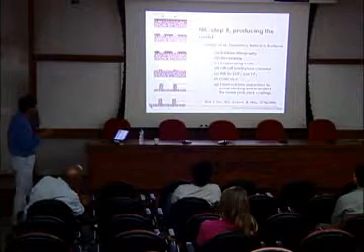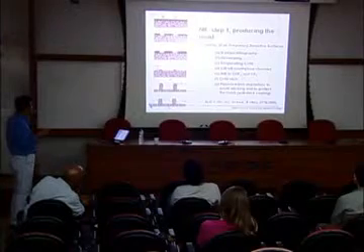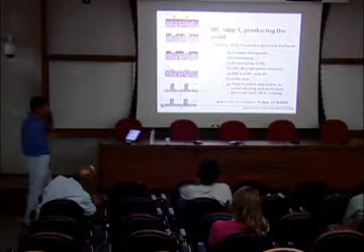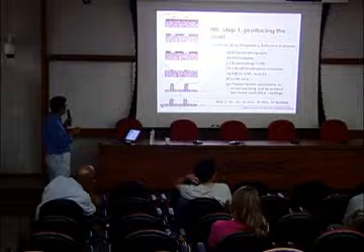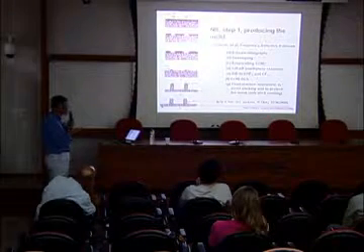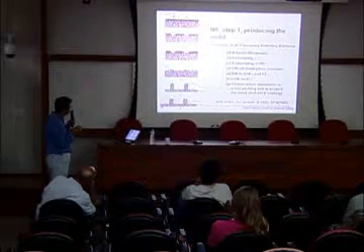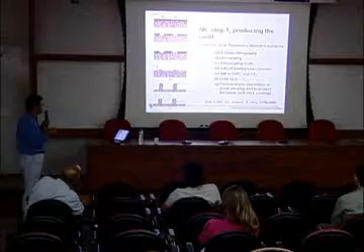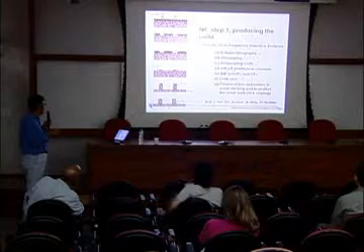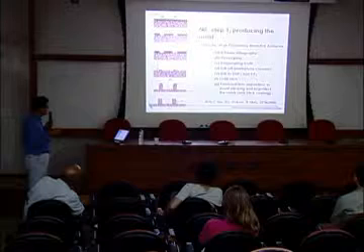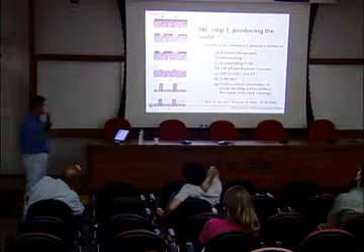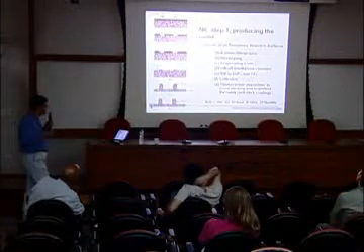And then after that, we can coat chrome and nickel by physical vapor deposition. Then we will see those small patterns, and then in solvent, all of those structures can be removed at the same time. Then we have all these small structures. Using this metal structure, we can do the gas phase etching. Then the anisotropic etching process will make this kind of structure. Then this is the mold.